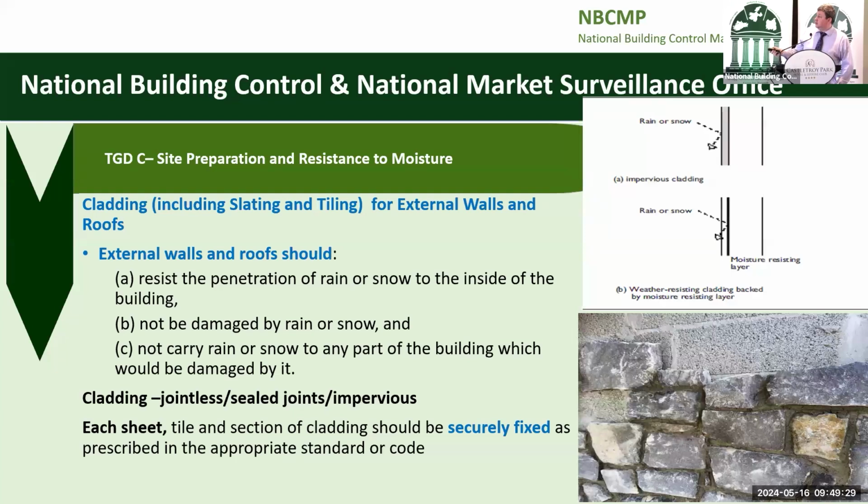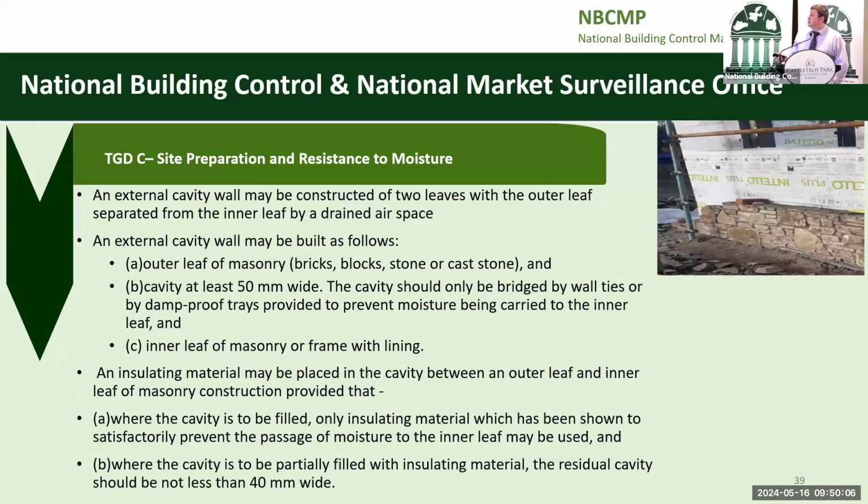You can see here, the block work, and they're just putting on the cladding. But if you go to the DOP for the block and how that is rendered, that wall would have to be rendered before they could actually put that on. Depending on the exposure location, it will need a render before that's fixed to it. Because that's a natural stone, it's permeable. It'll absorb water, and then you've moisture movement through the building.